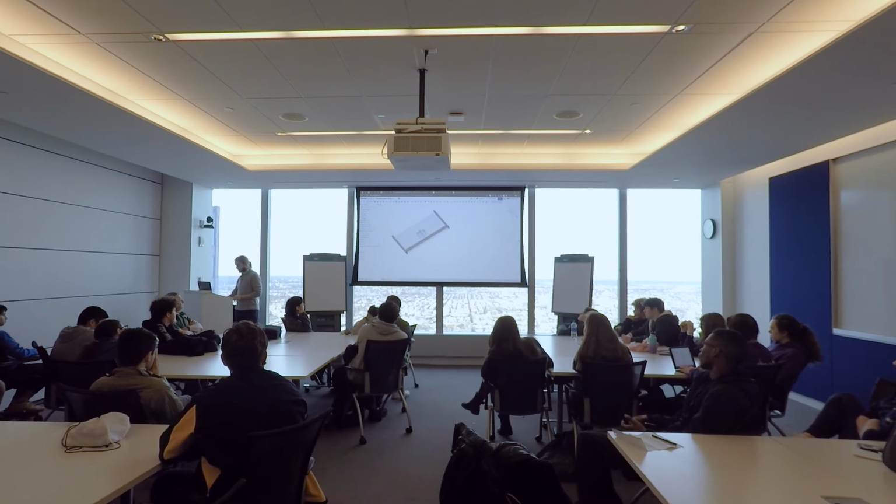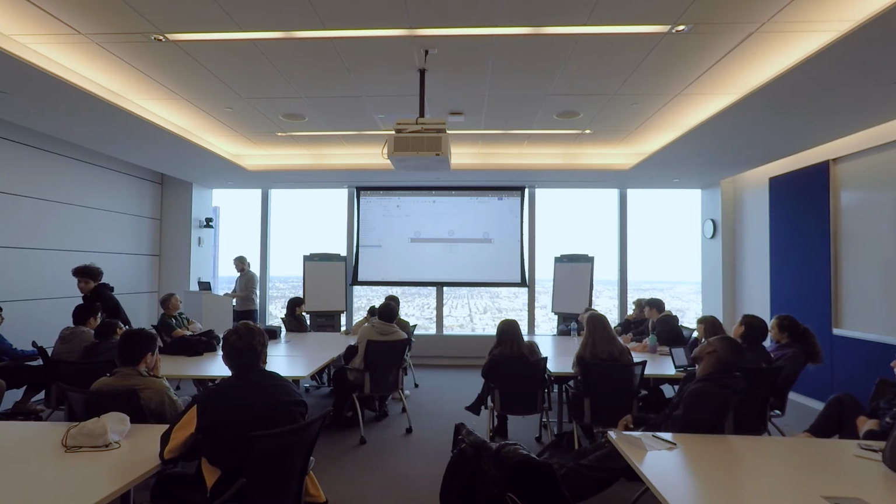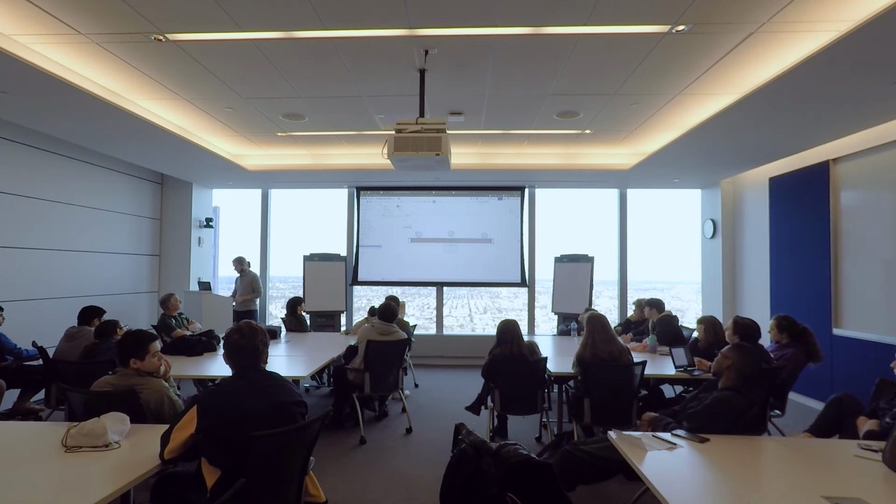For example, I can make a new quick sketch here on this space and then reference. I'm just going to draw them up here. You'll get the idea. I'm going to select all these wheels, make them all equal to each other, and I'm going to make them equal to this wheel too because that's exactly the size that I want. Or no, I don't want to make it the same. These are my bearing holes. That's right. But if I just dimension one, the size of the bearing, now they're all the same size.